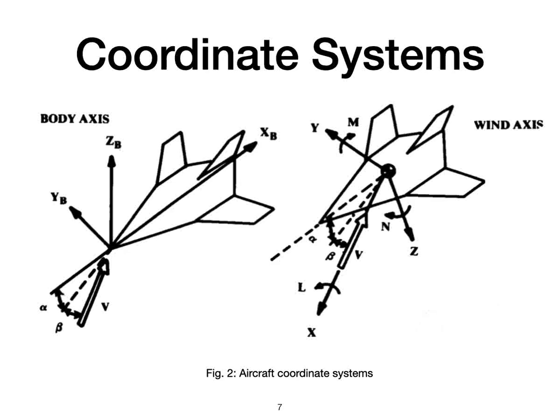The body axis system is rigidly fixed to the aircraft with the x-axis aligned with the fuselage and z-axis upward. The origin is usually at the nose. The body axis system is more neutral for most people but suffers from variation of the direction of lift and drag with angle of attack.